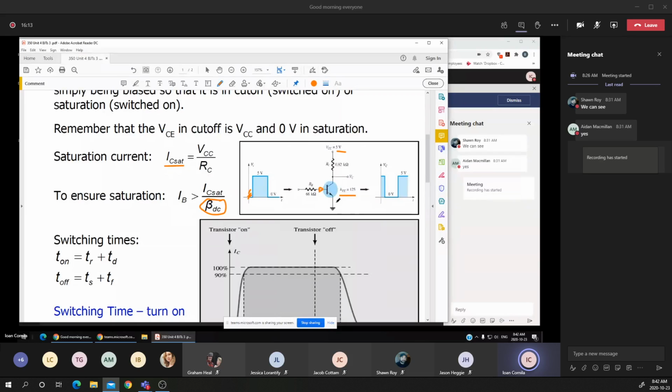The transistor is turned on, which means that the collector-emitter voltage is almost zero, so the VC, or the potential at the collector, is equal to zero. And vice versa, when the lowest voltage, or zero voltage, is applied again on the base, the transistor is turned off, and the VC becomes the maximum voltage, or the supplied voltage, 5 volts.